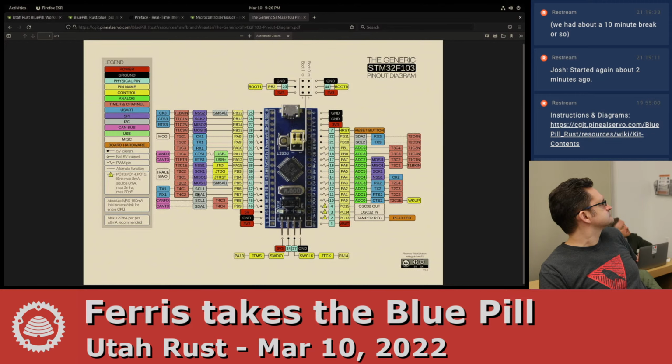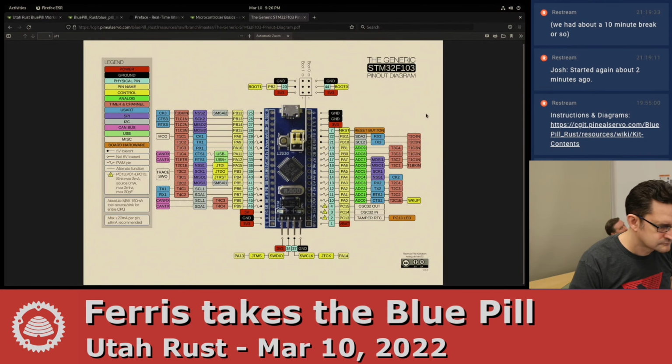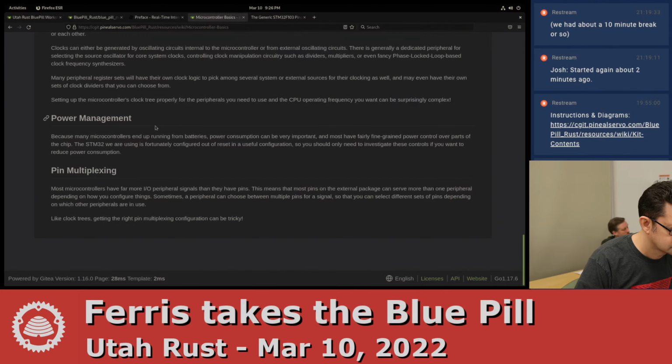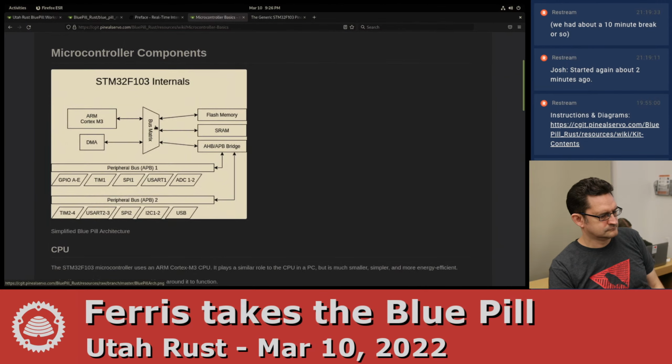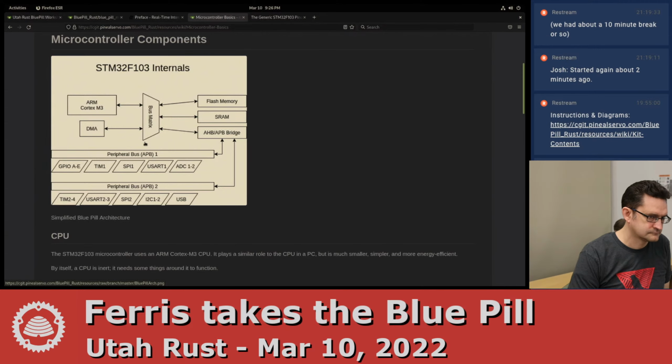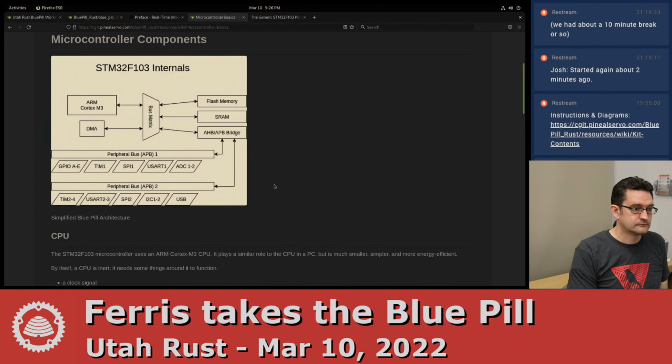In order to operate the display, the microcontroller has to be told to select this functionality for this group of pins. When that door swings and that group of pins is active, they cannot be used for any other function. In some cases, other pins are also locked into a particular function, potentially some pins you didn't even need.